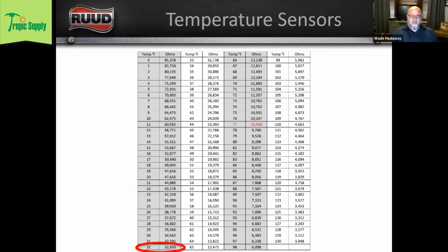traditional heat pumps struggle at 35 degrees and below. They can still pull out heat, but it's hard for them to gain too much capacity. And if you think about why, as the outdoor temp drops, there's less heat available to pull out of the air to move inside. So the colder it gets outside, the harder it is to pull out that heat.